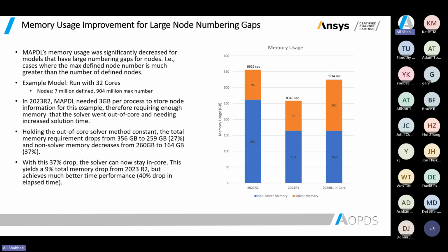For those that are not familiar with the in-core and out-of-core, basically, if you have enough RAM on your computer, on your hardware, then your solver will do the processing faster. If you do not have enough RAM, one of the things that can happen is the information should be written in your storage, in a disk on your computer, and that information needs to temporarily stay there so your solver can communicate between that information and your RAM and basically solve the increments to move forward.